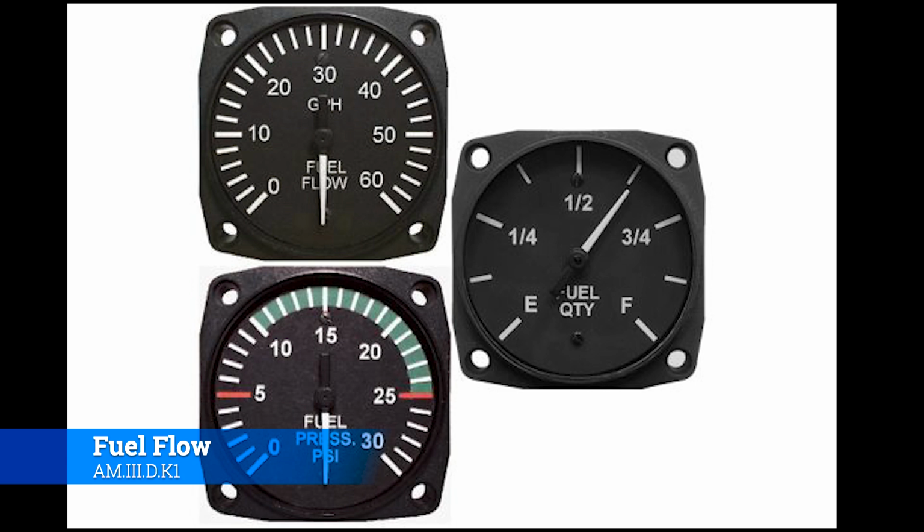It's just a little gauge that has an arm that sticks up into the green there, to let you know that the fuel pressure is positive and it's running at about so many psi, and you can infer that's about right. The gallons per hour is just telling you how many gallons the engine is using per every operational hour, and that will also help you with your flight planning, because you'll be able to say, well, I know I have 100 gallons left and we're burning 10 gallons an hour, so therefore I can fly for another 10 hours, and if I'm going 100 miles an hour, then I know I can fly 1,000 miles based on these fuel settings, provided nothing changes, and then you can make adjustments accordingly.